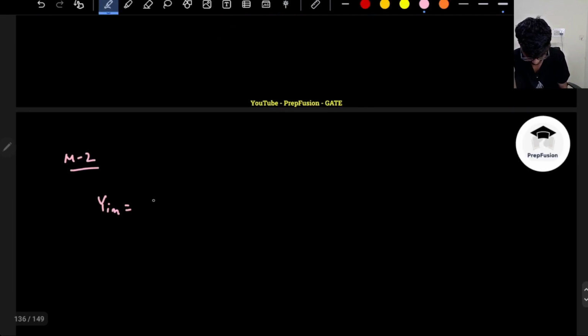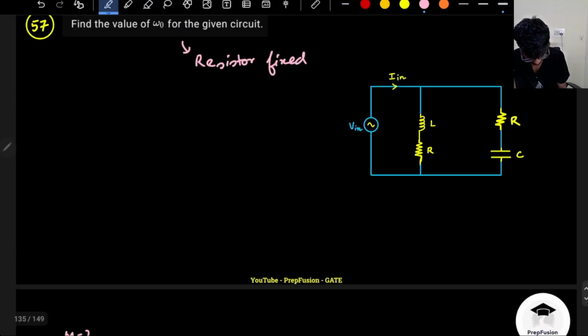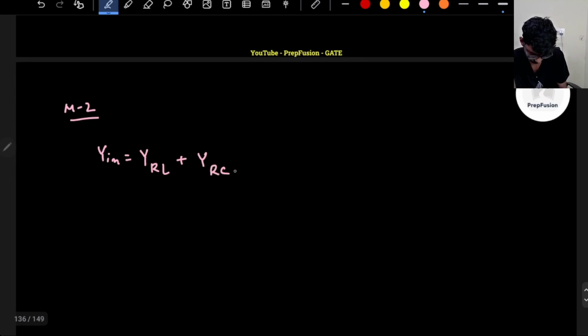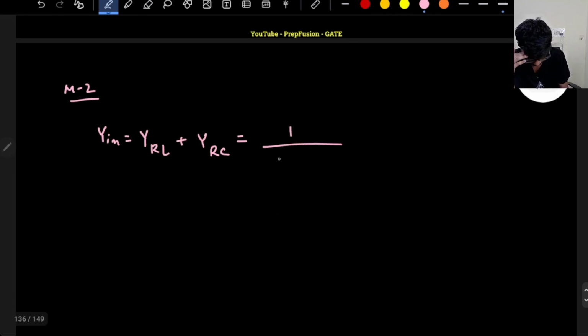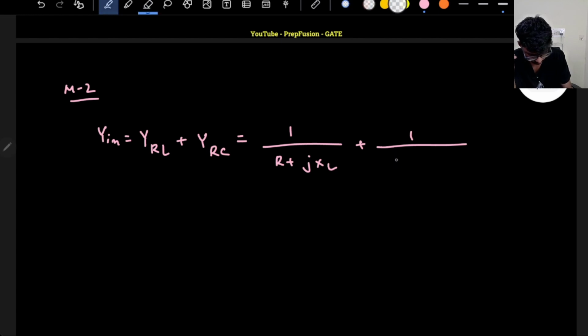Y in will be Y RL plus Y RC. So what is Y RL? It will be 1 upon R plus jXL, and Y RC will be 1 upon R minus jXC.